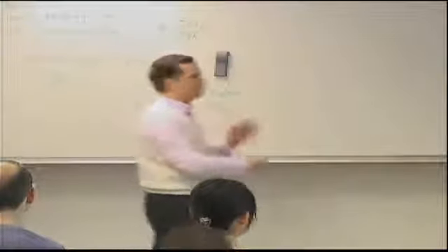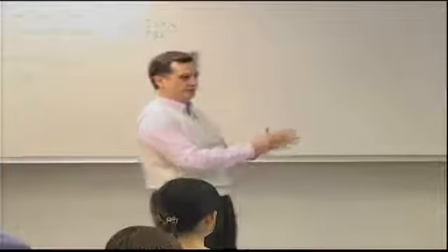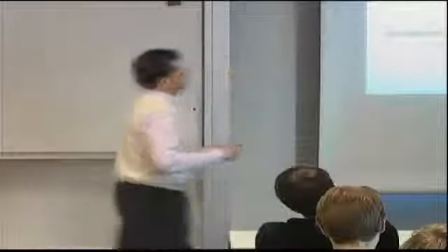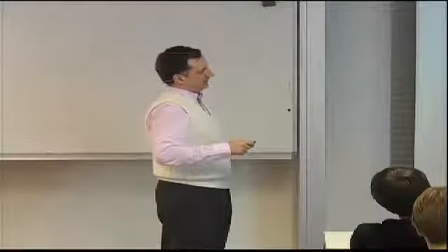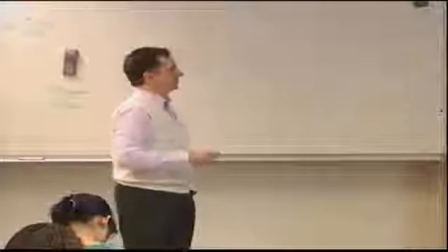But for our post-buckling calculation that we used to determine b effective, it was a slightly different boundary condition. It was still simply supported in terms of out-of-plane displacement, but it also was constrained in the in-plane direction. So there is a bit of an inconsistency here, but the main message will still be the same. If you refine it, you get about the same answers. The skin stiffness is 1 divided by little a11 for the skin and the skin thickness. So when you do that, you find 41 gigapascals.